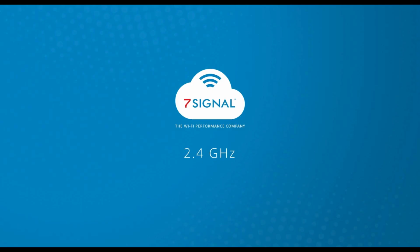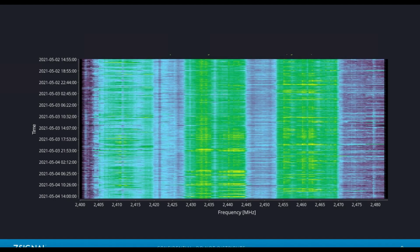All right. So with that said, we are now going to dive into a few of these, and first we're going to take a look at the spectrum analyzer charts on the 2.4 gigahertz spectrum. All right, and we're going to start with a real simple one first, right here. So here we go, guys. Now, as you can see, once again, time is on the y-axis, and what I'm looking for here is the 3 columns representing channels 1, 6, and 11.